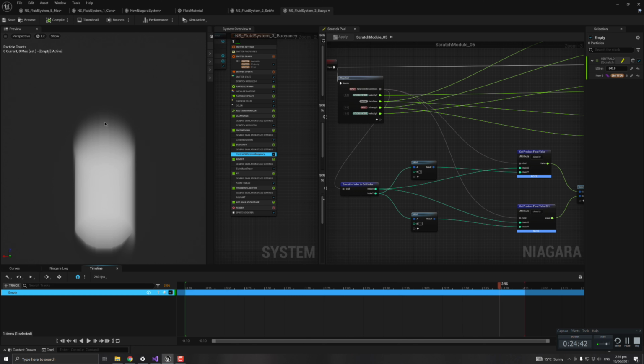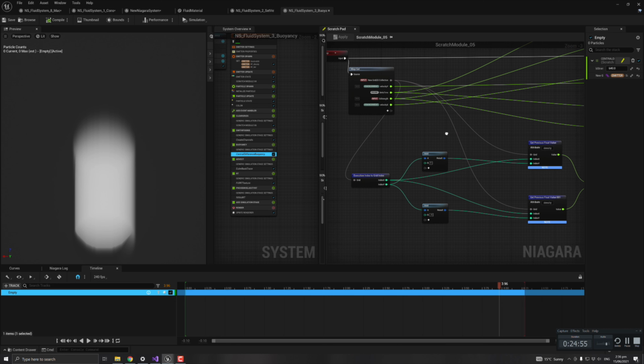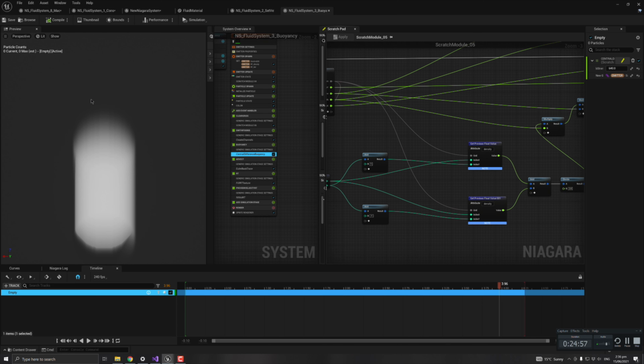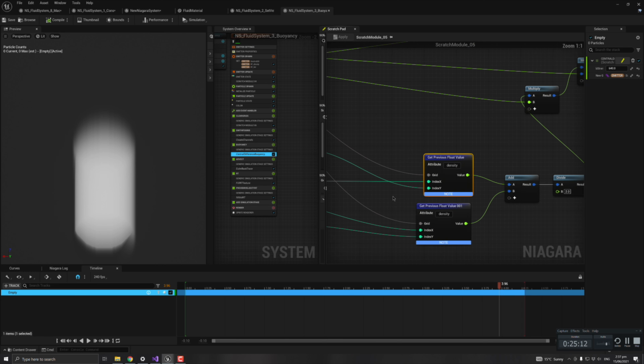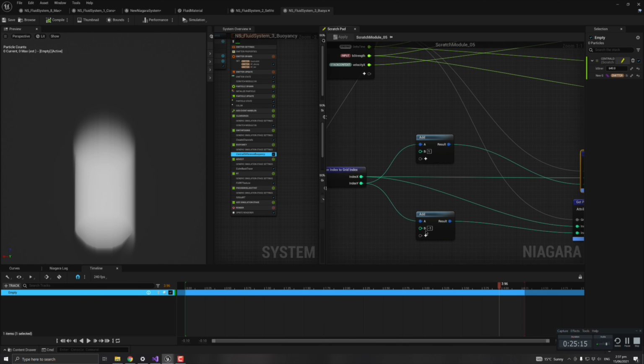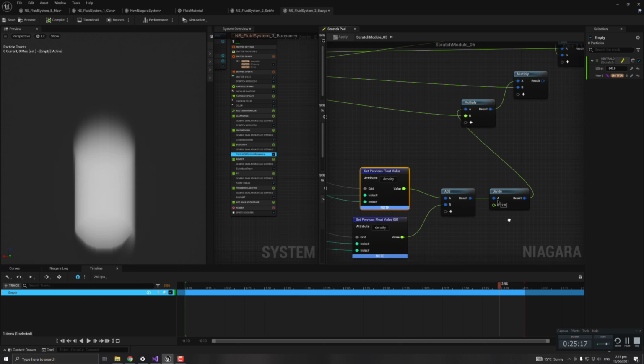So a lot of buoyancy systems in fluid solvers sample the density and use that as a way to signify that this area needs to rise or fall depending on what coefficient you put in. But that's not enough in this system, because if it's in a region of space out here, it doesn't necessarily know that there's density from below pushing up, because there's no rising pressure force or anything. So what I initially did was this smoothing attempt where it would sample above and below the current voxel and then average them out by dividing by 2.